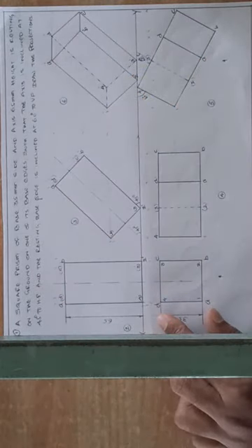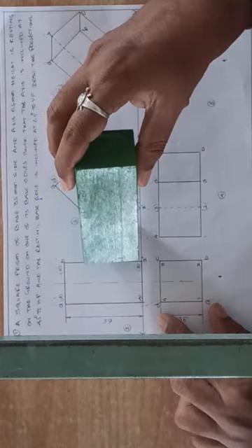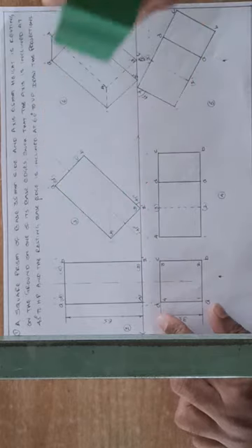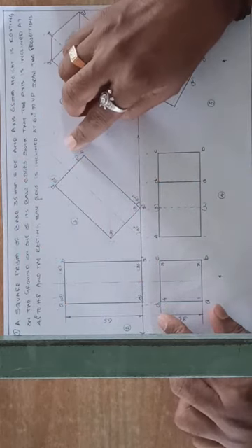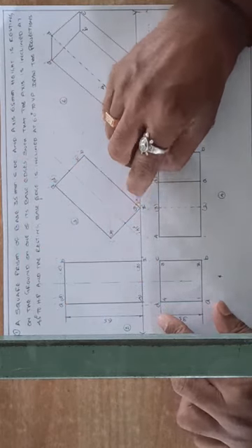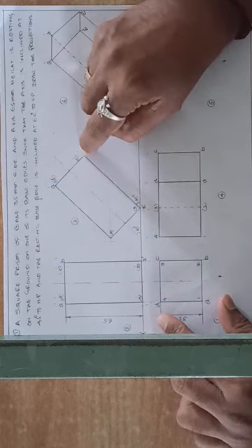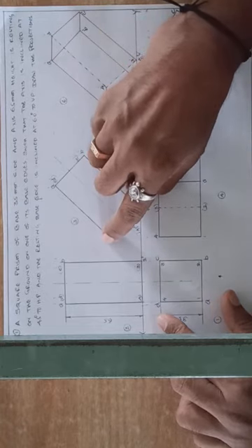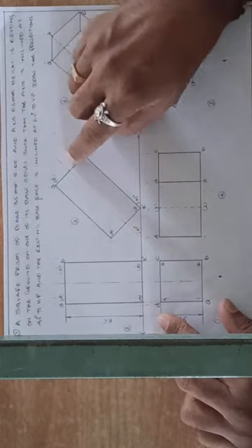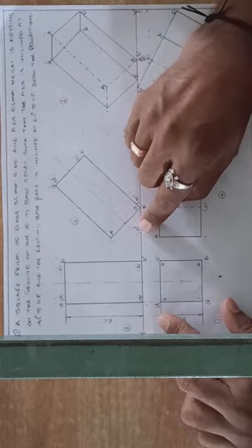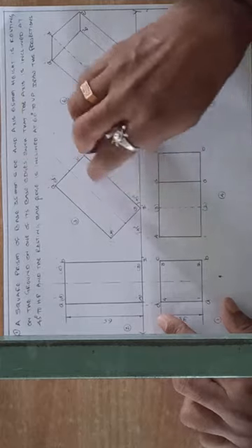These two are imaginary. Now, this axis is making some inclination, that is 45 degrees inclination with the HP. Then tilt this front view to an angle of 45 degrees. So axis 45 degrees means the prism's lateral sides are also at the same inclination. So take any point here, first draw the lateral side, then perpendicular base 90 degrees, then close it. Same distances you take and close it. And here also the axis. When you extend the axis and measure the angle, it will be exactly 45 degrees only, because all these are parallel.